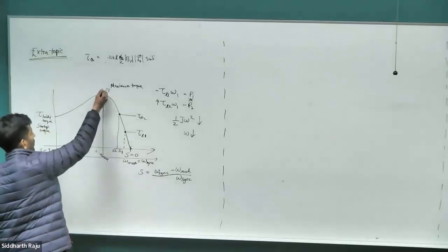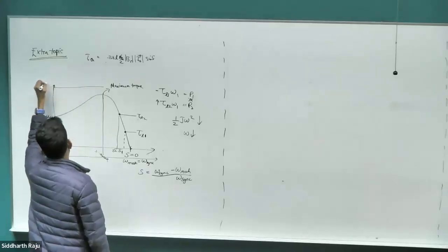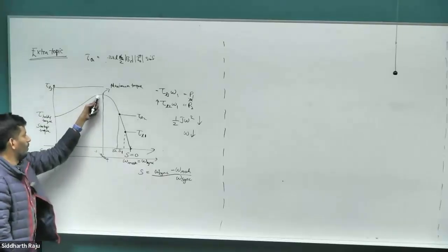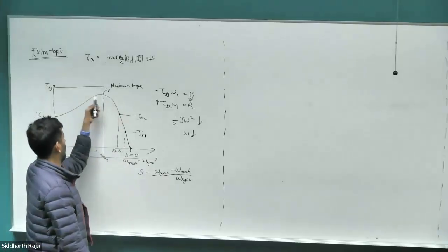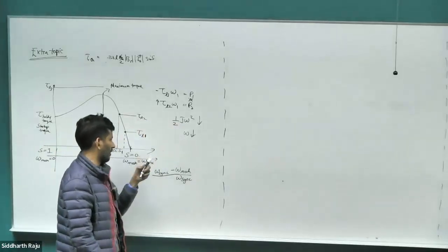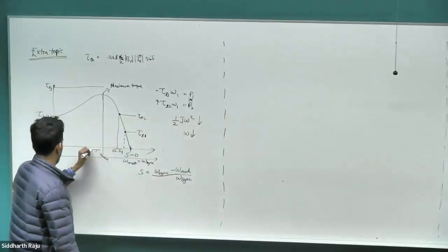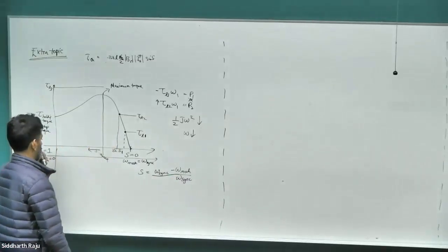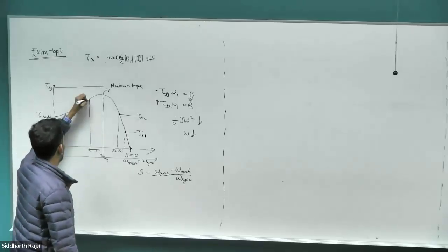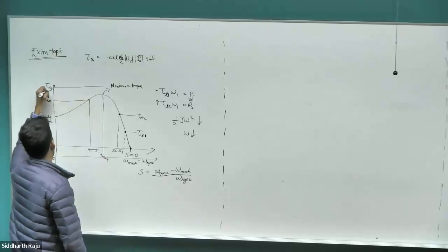Once it goes to this maximum torque, and let's say you demand more torque, if your load torque is even further higher, then what is going to happen? Since it's asking more torque than is being produced, it's going to take power out of the inertia, and the speed will start to slow down even further. If the speed goes down even further, slip increases even higher, goes closer to 1, and it comes to a new operating point. At this point, if you look at the electromagnetic torque, tau em, the deficit is even greater than what it was before.